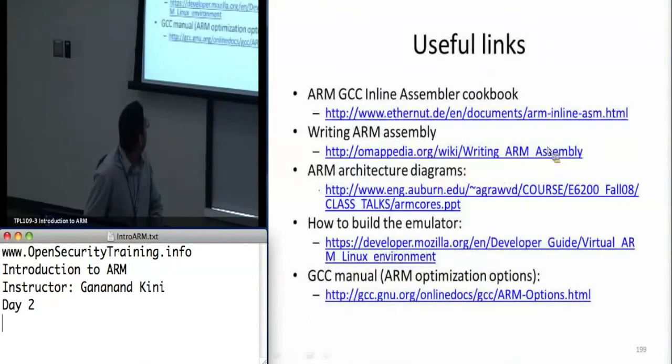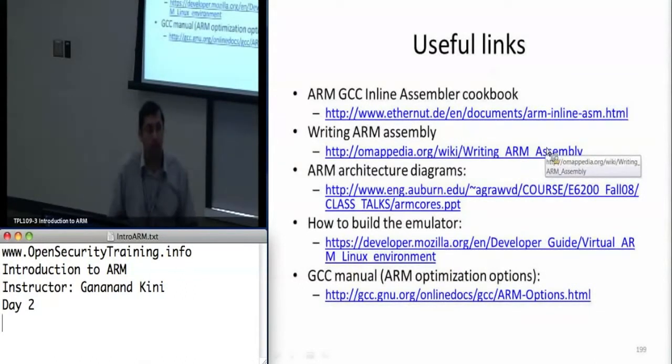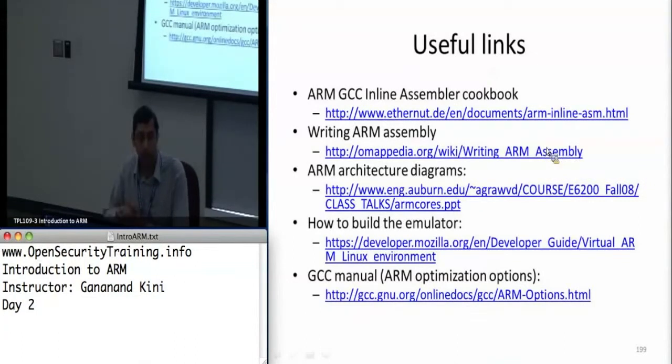So with that, I've also included some useful links, and this concludes the class. In retrospect, we started off with what happens at power on with these ARM boards. You enter the reset mode, right? You're in supervisor mode, and then you start executing, generally the bootloader, at a specific address. And once the bootloader loads, it runs the kernel and loads the RAM disk, starts running that, and then you can run whatever OS on top of the kernel, whether it's Android or Linux.